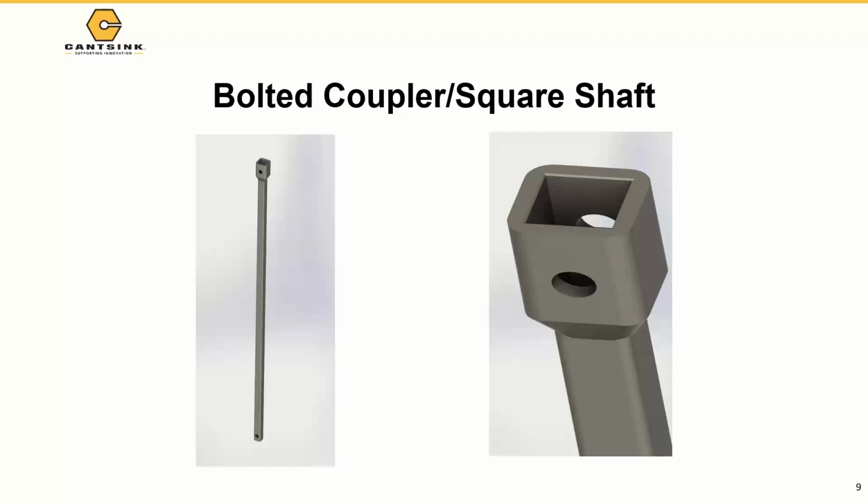There is only one manufacturer that has a threaded coupler, and there is another one in Canada that has a welded coupler. Okay, I've seen them. They go to the field, install the lead section, put the extension on, weld it, and keep welding the other extensions. The welder takes about maybe 10 minutes to weld the extension to the lead section or the extension to the extension.